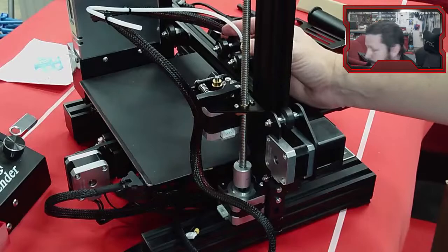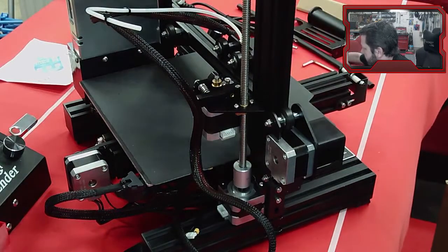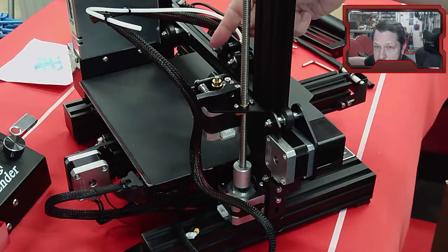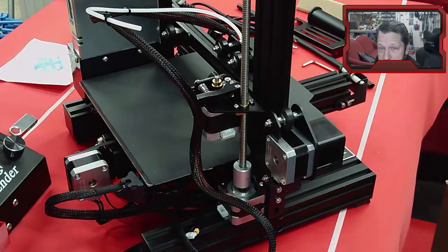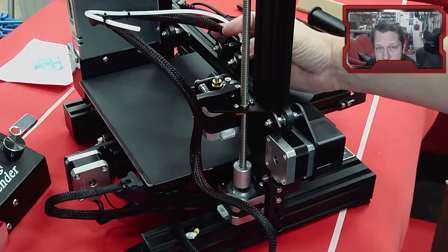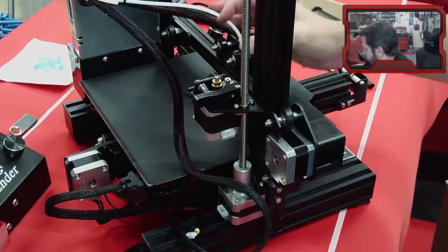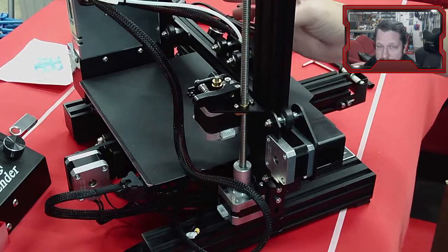The good part of that is there's no tube like this where filament can basically act like a really long spring, so you have more control over the filament moving. The bad part is it adds all this weight to the print head, so you have to print a little bit slower in general, because that print head has to move back and forth, and now you're making more weight that has to move back and forth.